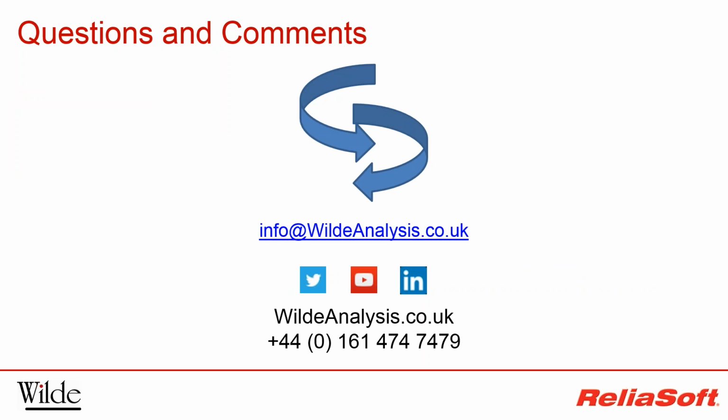How many people is best for an FMEA meeting? There are no real hard and fast rules as to how many people should attend an FMEA meeting. In some instances, FMEAs are performed by individuals, so a team of one can be effective. It's desirable, though, to keep the team as small as possible while getting enough different perspectives and knowledge about the item together. Generally, it can be difficult with teams above 8 people to keep the conversations on track and to come to a unified decision when moving forward. And so, generally, the larger the team, the more important it becomes to have some sort of facilitation there.